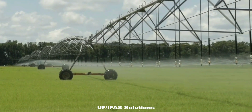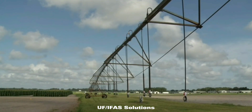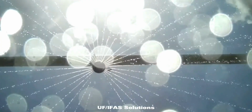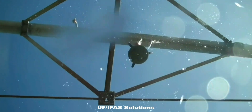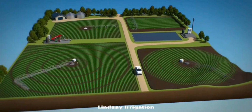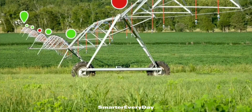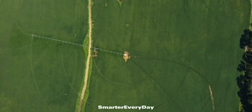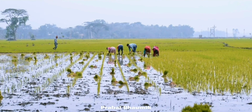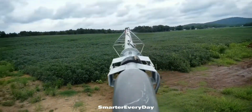This works by consisting of a single long irrigating pipeline attached to a central tower that moves slowly over the field in a circular pattern and irrigates the plants with sprayers or sprinklers that are placed on it at frequent spacing. The single long irrigating pipeline acts as a radius that revolves around its center. The radius of the pivot can be adjusted depending on the size of the field and the crop being grown. By knowing the radius of the pivot, farmers can calculate the area of the circular field being watered and adjust the amount of water being applied accordingly.